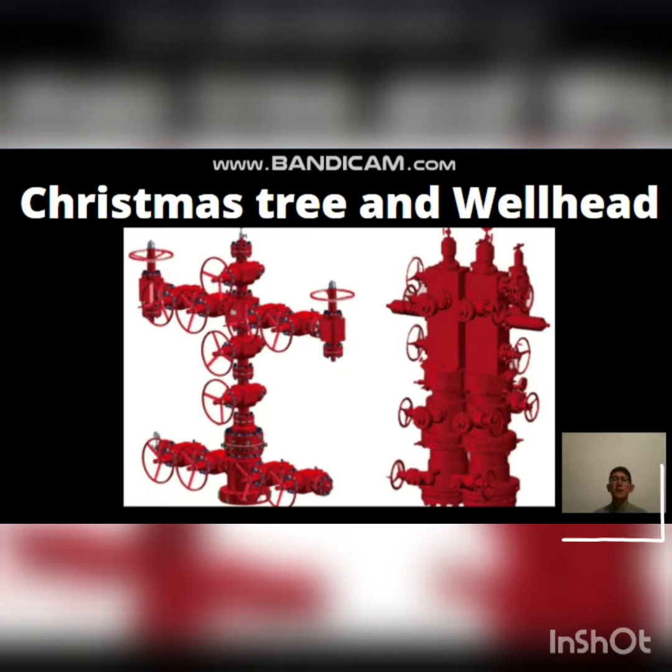Let's move to the Christmas tree and wellhead. So Christmas tree and wellhead, they are not the same because their purpose is different from each other. Christmas tree's purpose is to control the flow of fluid on oil and gas well, and the wellhead's purpose is to control the pressure.